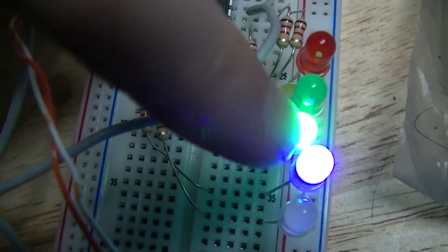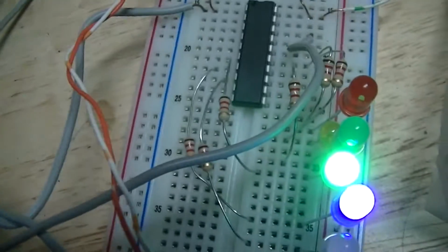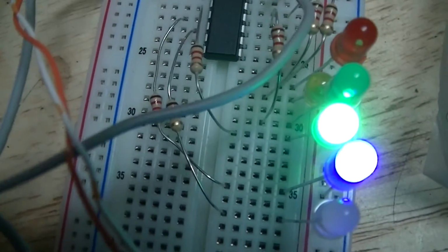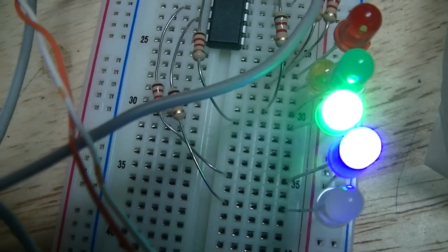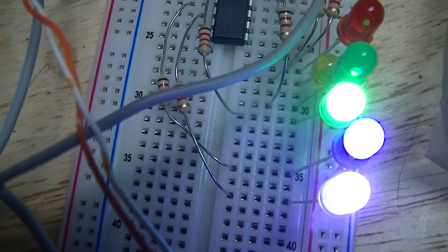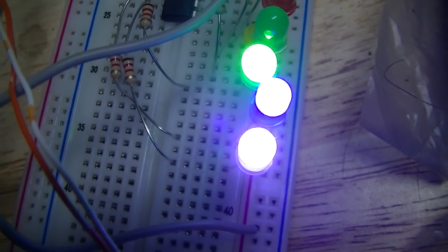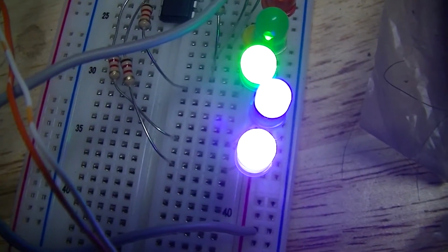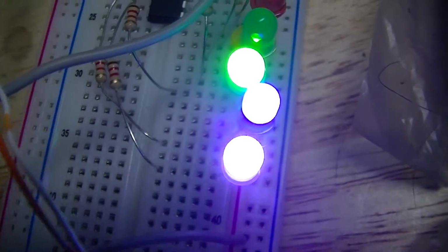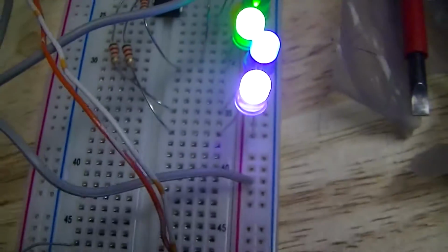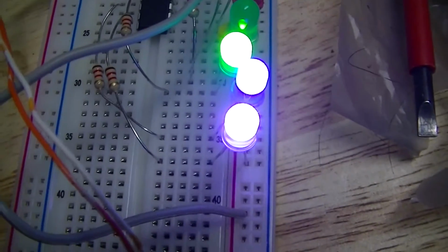Then it gets up to about 13.1 volts. I don't remember the exact specifics, may need to recalculate them. But then it turns on the second green LED. This would be when it's charging. And then if it gets up to about 14 volts or so, it turns on a dump load, which is represented by the white LED,